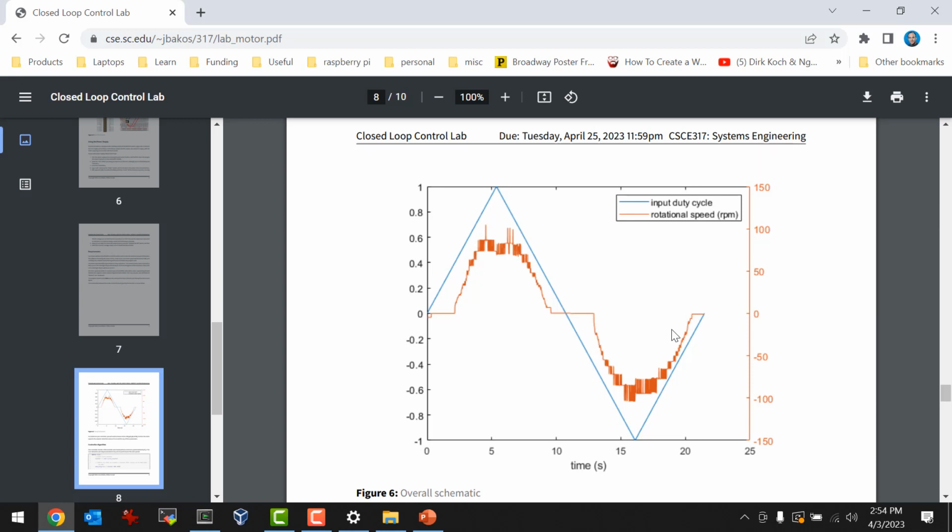So that encoder is going really fast. It's a high-speed signal. In fact, now that I think about it, I think I might have just figured out why this happened. When I measured this, I was only measuring the encoder at like 100 hertz, right? I might have just been measuring that thing too slow. That might have been why we got this discretization. But we want to be able to set that speed as well, the sample rate. You guys with me? So yeah, I think I might have just been sampling it too slow.